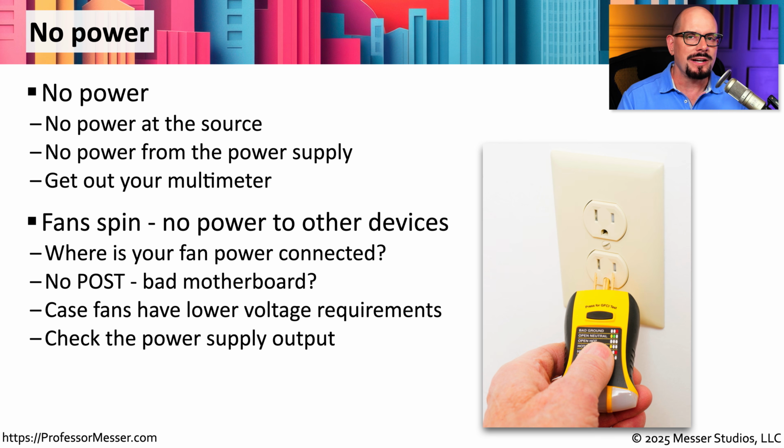And if the problem is that only your fans are working, it might be an issue with the voltage that's being sent out of your power supply. The fans themselves don't need a lot of voltage, but obviously the components on your motherboard need a lot more power. So you may want to grab your multimeter and check all of the different voltage outputs on your power supply to see if all of those are working properly.